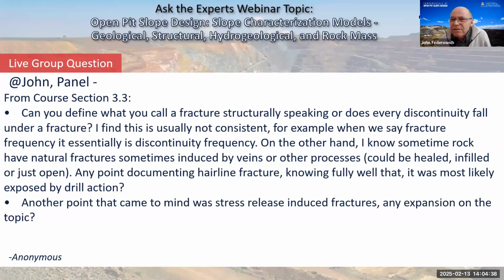Was that question to me, Felicia? Yeah, just for discussion, would you normally in a drill core log what you think are hairline or drilling induced fractures? I don't think we would normally. No, definitely. It depends on the scale and the scope of the project, of course, but micro defects are that sort of category. And if there's no continuity across the core entirely, then they're not really a fracture that needs to be logged, I would say.